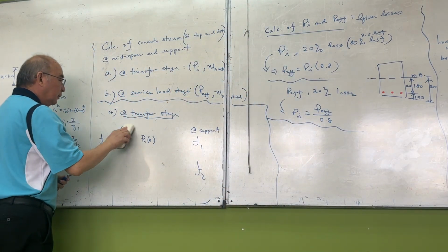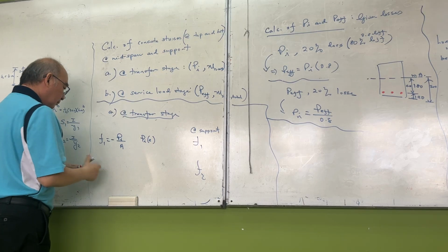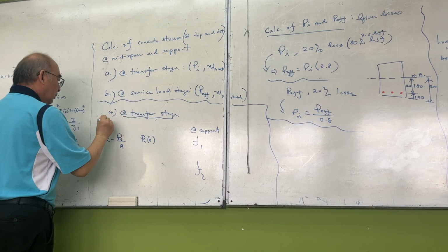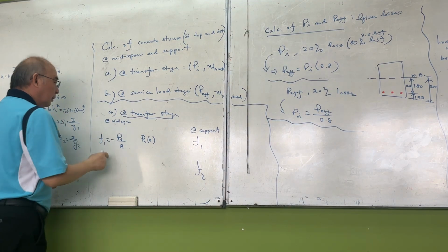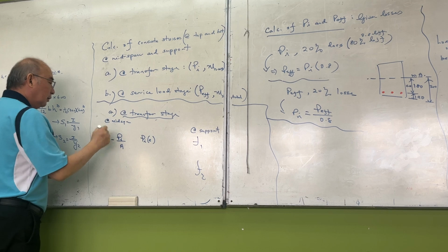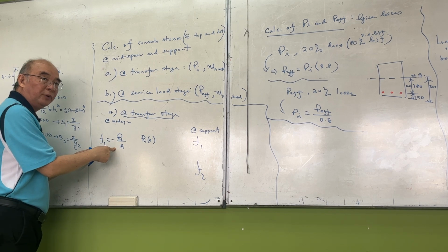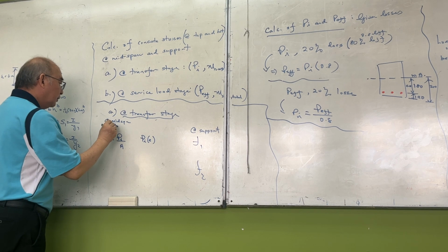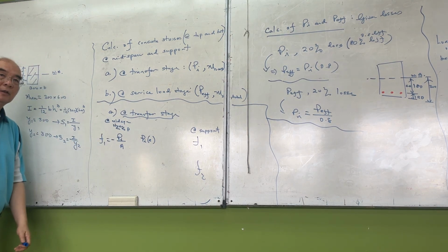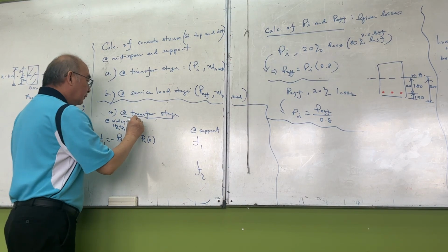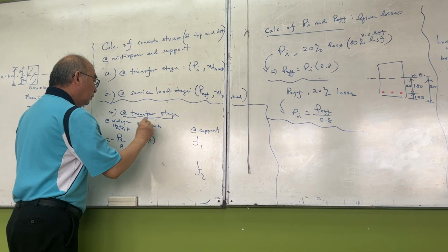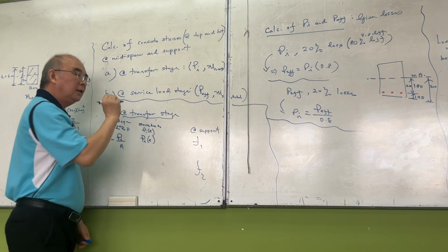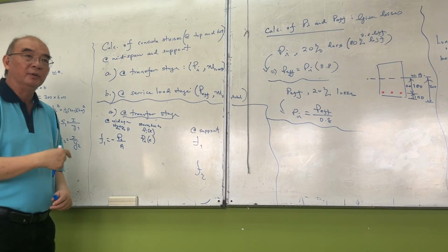Here at mid-span, the first term is the stresses due to P. The second term is stresses due to P times E, the pre-stressing moment.